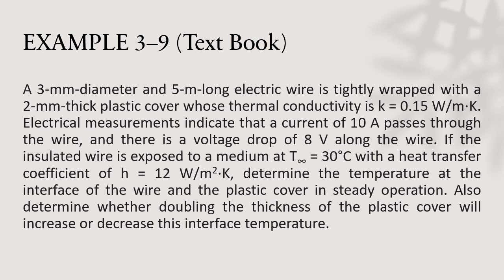If the insulated wire is exposed to a medium at 30 degrees C with a heat transfer coefficient of 12 watt per meter squared Kelvin, determine the temperature at the interface of the wire and the plastic cover in steady operation. Also determine whether doubling the thickness of the plastic cover will increase or decrease this interface temperature.